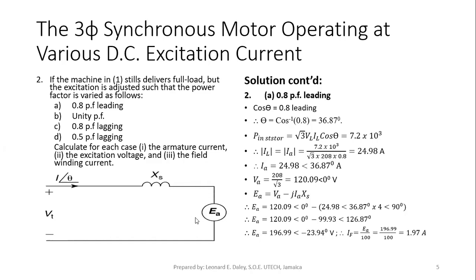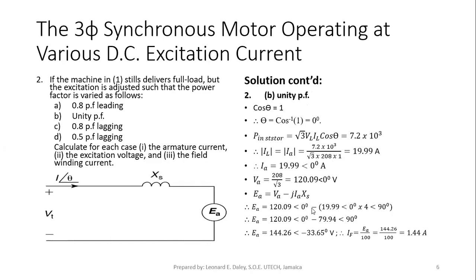So EA is an induced EMF on the stator windings, but note that the stator also has a supply voltage, the three-phase voltage supply connected to it. So the induced EMF acts like a back EMF or a counter EMF to the supply voltage. Okay? Yes, sir.